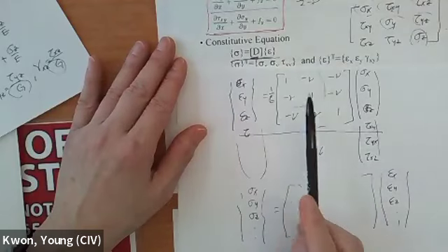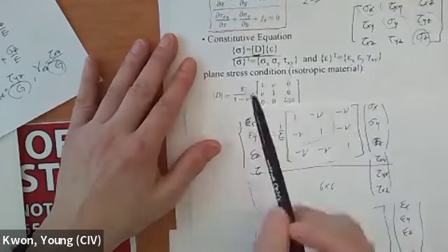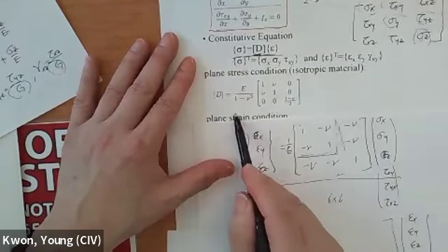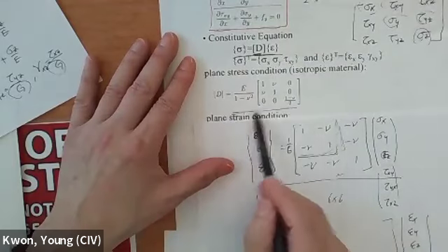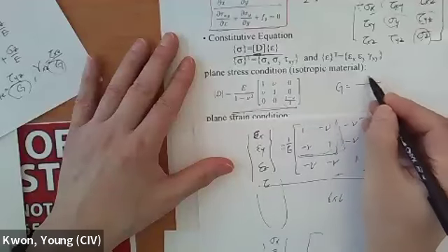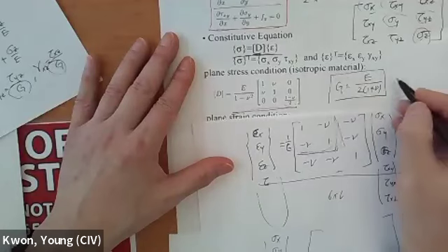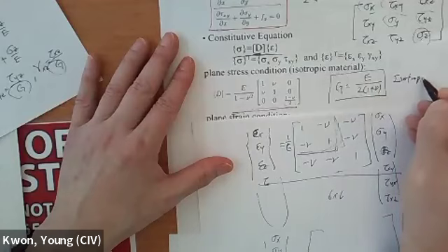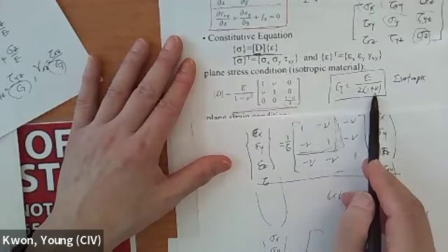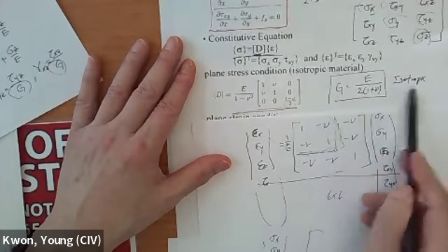Okay, so in isotropic material, inverse of that is going to be equal to D, and especially plane stress, only looking at this one, right? Then inverting that is going to be equal to theta. Okay, that's the shear modulus. So in other words, the shear modulus for isotropic material has relationship like this. So in other words, shear modulus is not independent. If you know elastic modulus and Poisson's ratio, then you can calculate shear modulus from here. It's not an independent property for isotropic material.